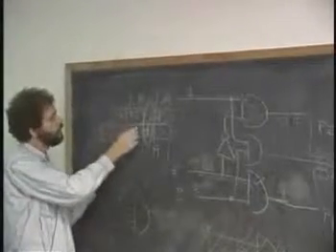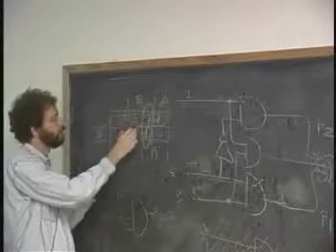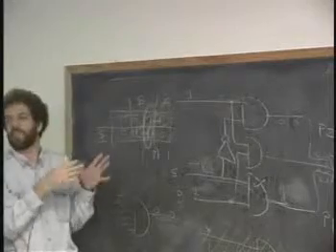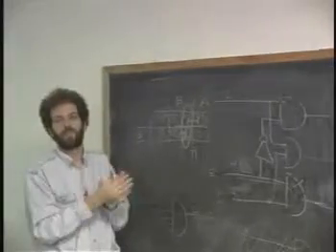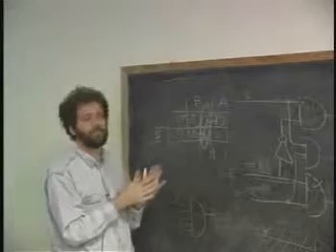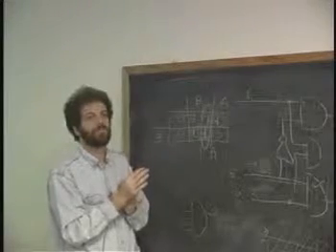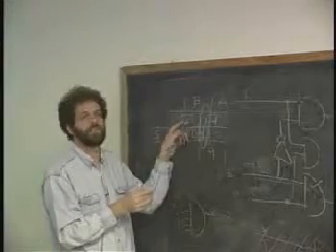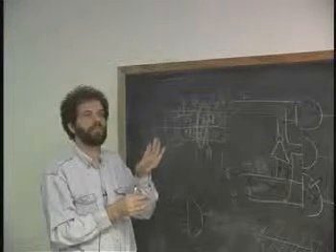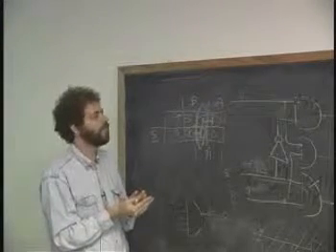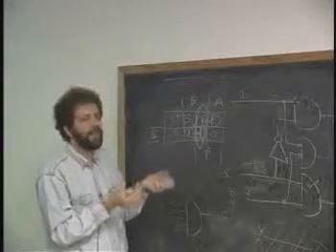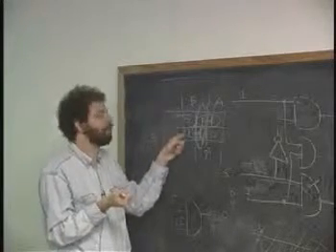Now, in terms of what happens when you go 1 to 0 and 0 to 1, we're not going to talk about that. That may, in fact, glitch all over the place, but we won't worry about that right now. What it actually involves is the question of how many AND terms turn on when you go across one.